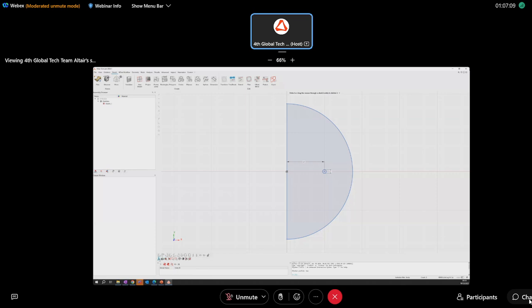So you can find the possibility to use the different views, predefined views. So clicking just on the first icon, you can use them. Then we have the possibility to capture the view. The fit tool, you can just press F, is very useful. Then we have the zoom. For example, we want to use the zoom, we can just click on it. And you can come back with F or just fit the view. We have the possibility to change the visibility to the entities and the cutting plane, but I think these tools could be useful later. And apart from that, yes, we can ask from the sketcher. As you can see, the background is the one of the sketcher, so we can press ask. Okay, and we can click on it and recreate.